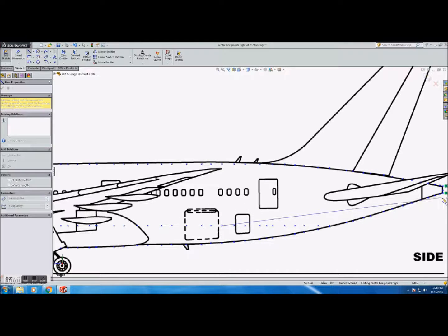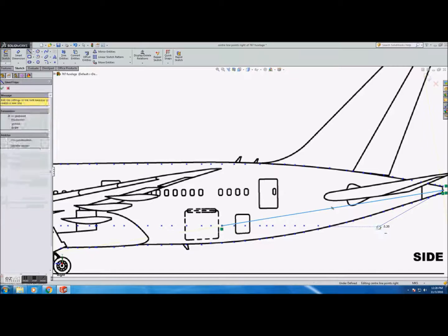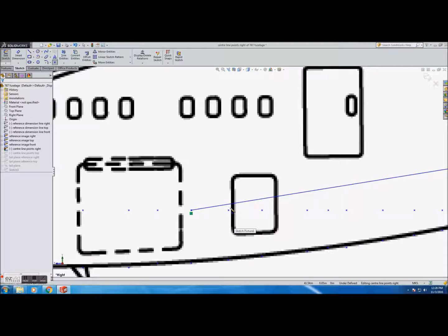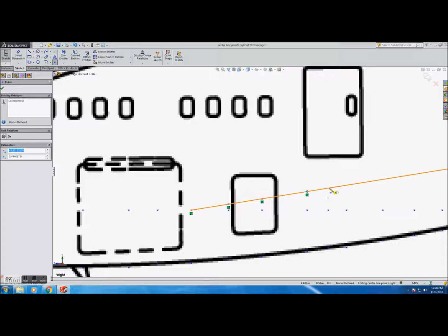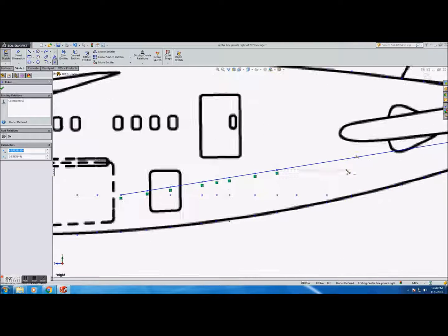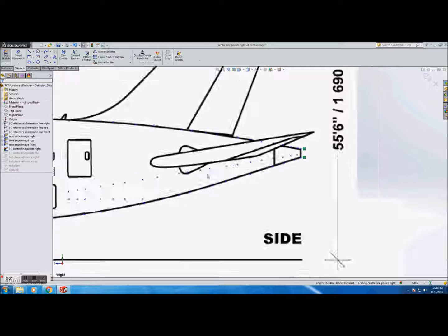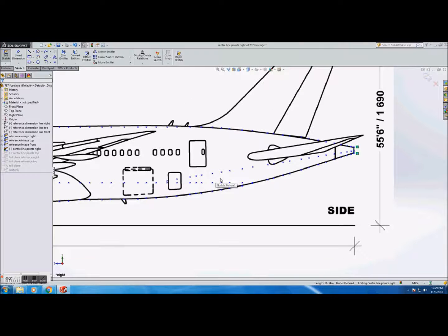So naturally, before we can start doing any of that, we need to make sure that everything's still lined up with the original points that we plotted. The way that we're doing this here is that we're just moving into a right plane centered sketch first, to make sure that all the lines line up with the line that the angled plane is on. But then from there, once we've got that, we can directly copy the points over, or go over the points again in the same space, but on the new plane, the angled plane. And then from there, we can move on to copy the outline points.